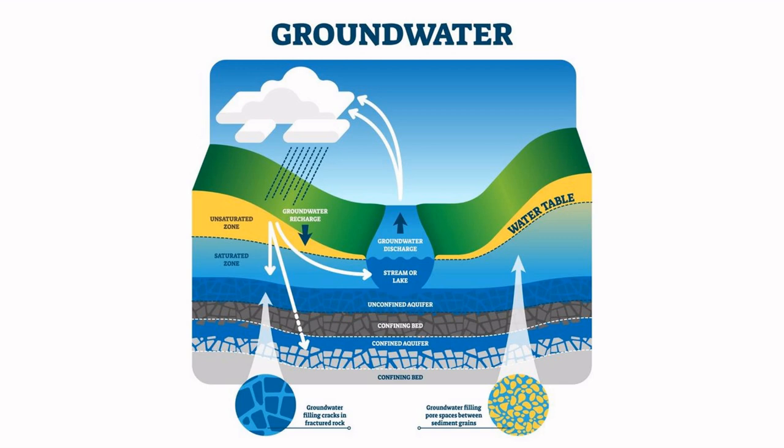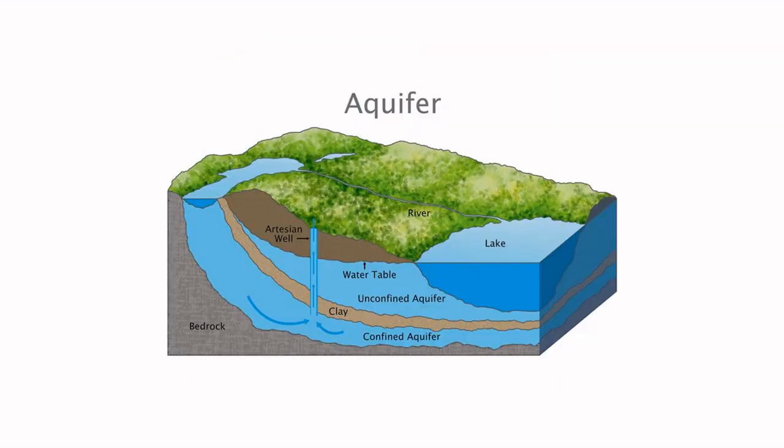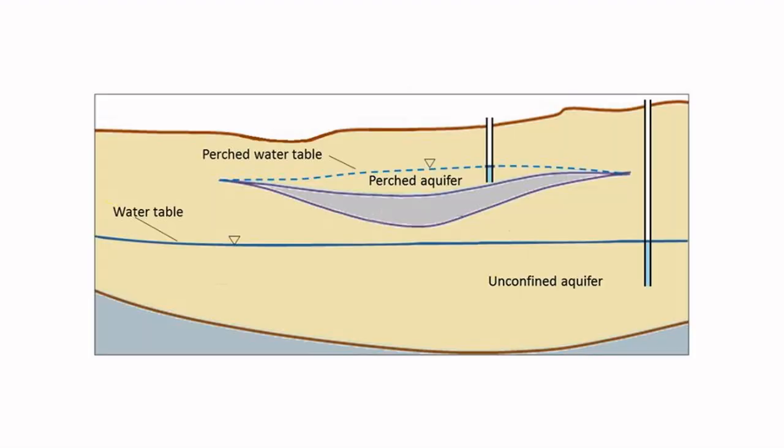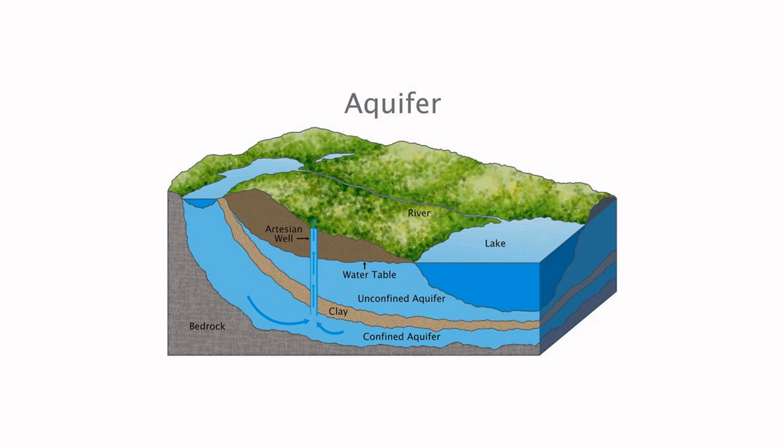An intermediate zone commonly separates the saturated zone from the soil water. The water in the soil zone and the intermediate zone is called suspended water or vadose water. This water is in downward motion under the influence of gravity, so we can call it gravitational water also. The intermediate zone may be absent in most environments, and in arid zones it may be more than 1,000 feet thick.